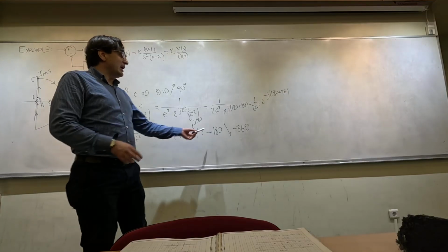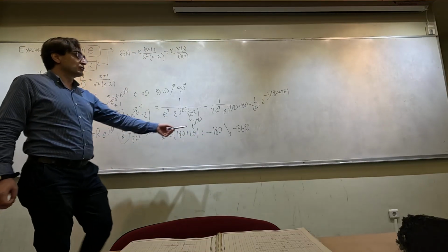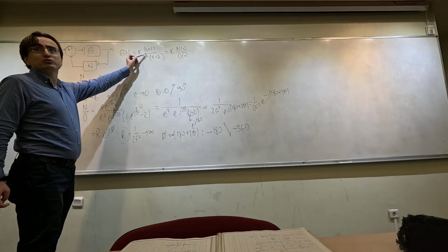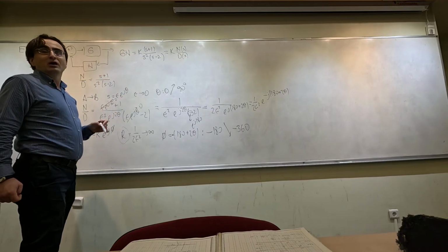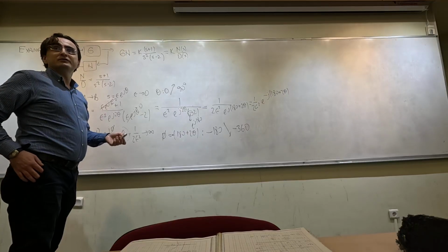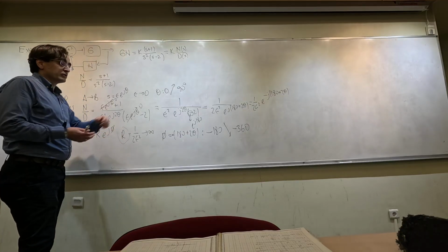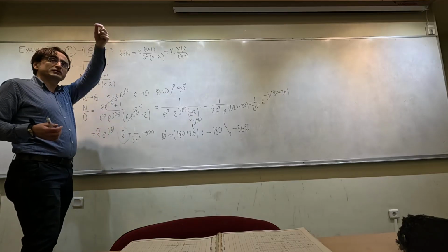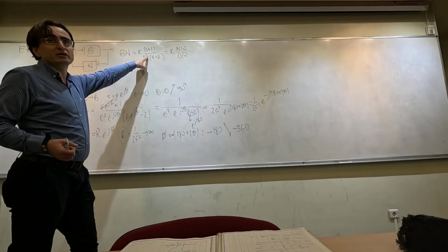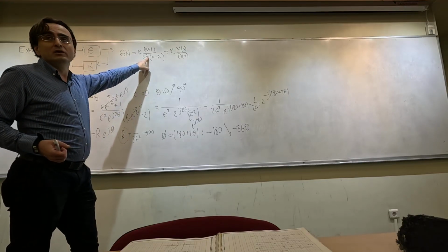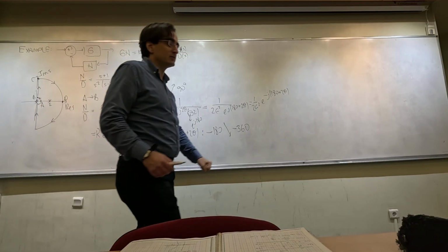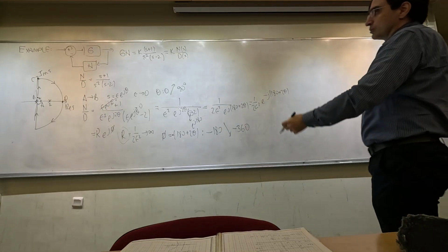So now here I see that at radius infinity, I need to turn 180 degrees. If this was cube instead of square, how many degrees should I turn at infinity in that case? Yes? 270 degrees. Okay, so the number of degrees that I turn is determined by 90 times this power of s. If this is 3, I'm going to turn 270 degrees. If this was 4, I need to turn 360 degrees, etc. at infinity. So now let me go to the other part.